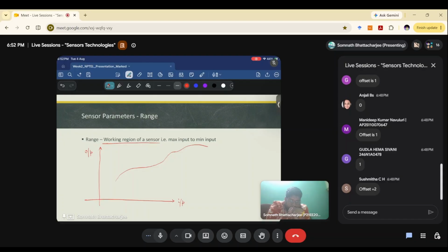Why do we need that? Let's say this is a temperature sensor or something like that, and this is at 50 degrees centigrade. At a specific point, we need to do this. If the linear fit is x1 and this variation is up to x2, so the error is x2 minus x1, but obviously at a specific point. So at 50 degrees C, the error is this.